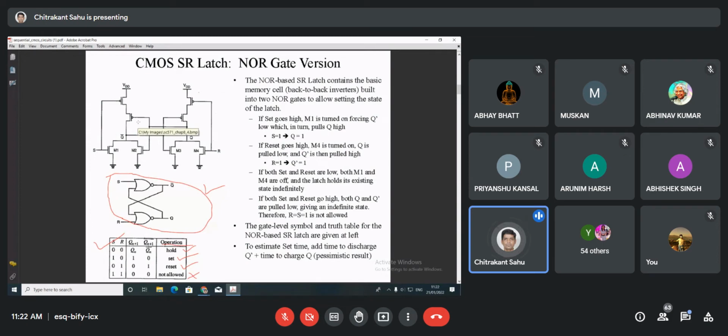Okay, so you can see how it can be built. Just see this diagram and you will be able to write it, because it is a NOR gate. Two NOR gates are there. This is one NOR gate and this is another NOR gate. So just prepare two NOR gates. While preparing one NOR gate using static CMOS logic, how many transistors are required? 4, right? 2 NMOS and 2 PMOS. So this is one NOR gate, two in parallel, and this is in series. Again, this is another NOR gate, two in parallel, two in series. Okay, and then the rest of the connections.